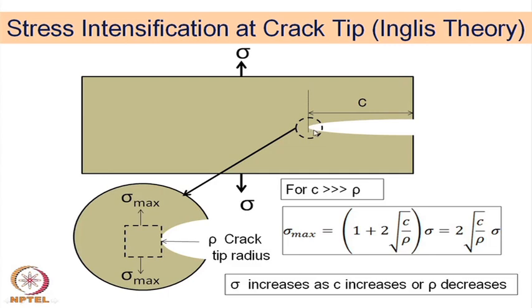ellipsoidal in nature, and this part has a much sharper end than the rest of it. Okay. So, there will be two sharp ends on the two sides. So, we are looking at one of these sharp ends. Right. This part has been magnified here, this particular circle. So, we are applying a stress, a kind of tensile stress in this case. We are trying to separate or expand this crack, and look at the magnified scale or magnified image here.